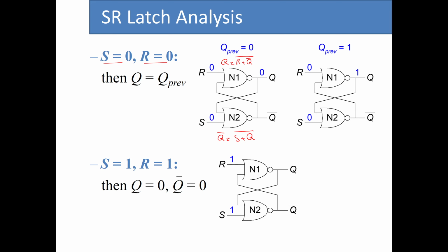So for the first condition, we assume that the value for Q is 0. Or more specifically, the previous value of Q is 0. A fraction of a second before we change the inputs, its value was 0. So now let's see what happens when we assume Q is 0, or when the SR-Latch is in reset state.